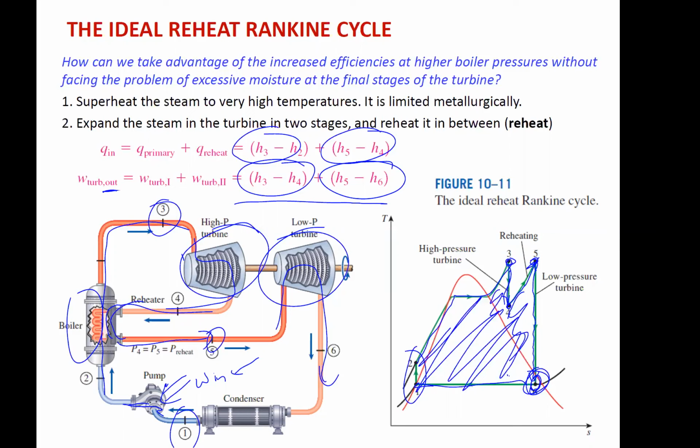So having a low pressure turbine allows heat out like easier. It's more about the turbine blades here. So the later stages of the turbine blades, by having that second turbine, by that reheat and going over here, we would normally be here, and it's not dealing with this part, it's dealing with this part that the turbine can't handle as well, okay, because of erosion on the blades.